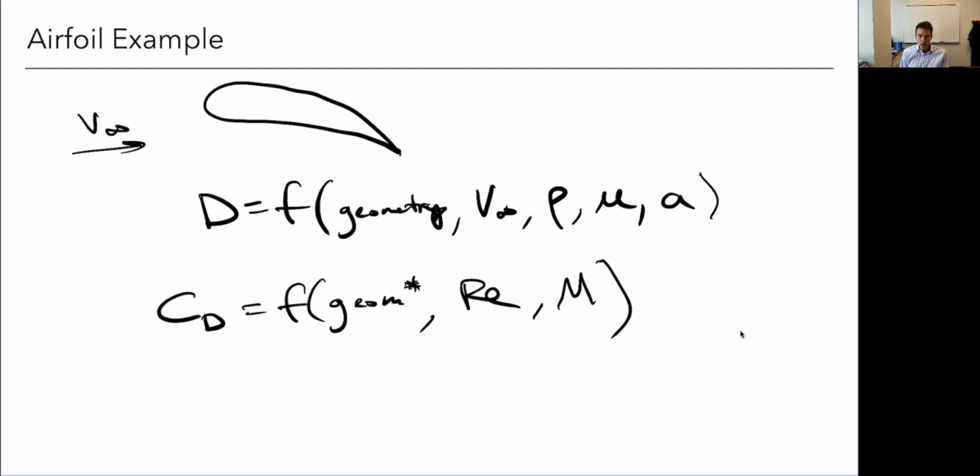But this is kind of the power of doing a non-dimensionalization: I could take a full scale vehicle, and if I use the same geometry scaled down but the same relative sizing, then if I can match these other parameters, I can predict its performance, in software or in an experiment or something like that. Okay, we'll see that that's actually sometimes harder said than done.